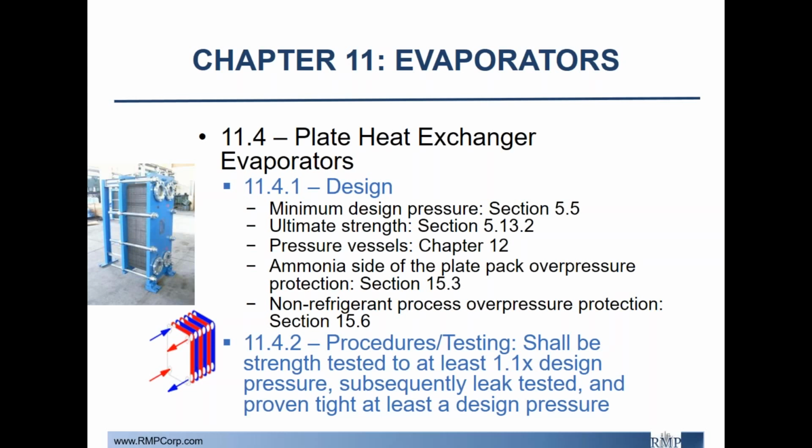As far as hydrostatic overpressure goes, again, where the inlet and outlet can be isolated, there must be protection. However, the exception is if the evaporator is not a pressure vessel. It can be protected in accordance with 15.6. So there is another exception there. Again, it's in the code. Feel free to read it and refer to it as necessary.